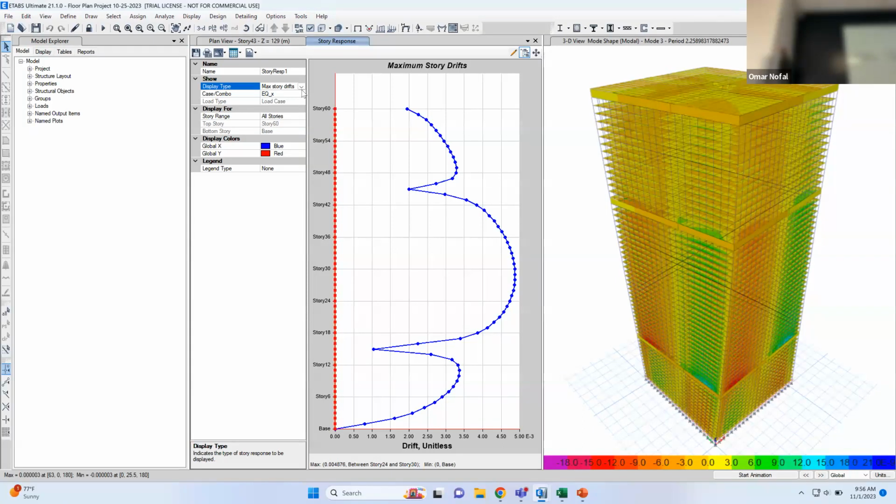Okay, if there's no outrigger, this is going to be something like this. You will not have these drops because the outrigger is very, very stiff. It didn't make differential displacement. The column is bending, but you have a very strong story, so it doesn't have that much interstory drift. So this is very important to show in your project for all the simulations that you have.